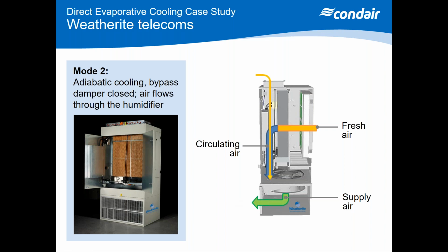So it's very simple in its design, and all we're doing is evaporating water off, in this case, a glass fibre porous material, where water is constantly replenished from a tank at the bottom of the unit and pumped up to the top of the unit. So the unit constantly has water cascading over the glass fibre matrix.